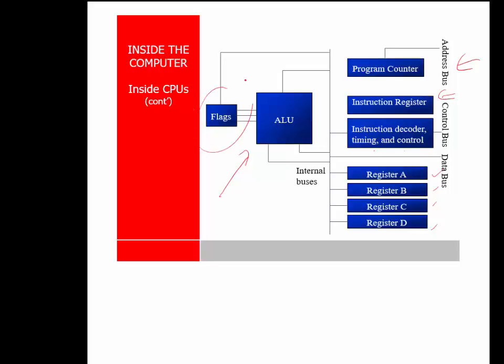And then on this side, we've got our flags. Normally our flags are also contained in another register called the program status word. The flags give us information like, was the result of the last operation negative? Was it 0? So in other words, you might see an instruction that says decrement and jump not 0, A, comma, start loop.